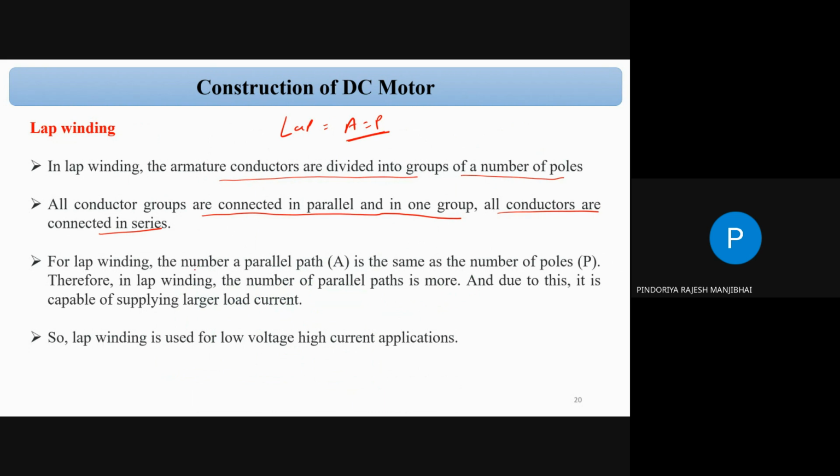Torque is directly proportional to the current. Whenever we put coils in series and parallel, you know that relation very well. Suppose you want to increase the current rating, then you connect in parallel. Suppose you want to increase the voltage rating, then you connect in series. So depending on the specification, we need to choose the series and parallel combination.